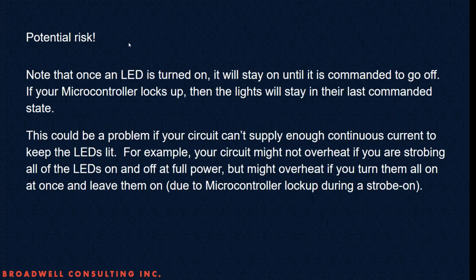One of the things we need to note here is a potential risk. Once an LED is turned on, it'll stay on until it's commanded to go off. If your microcontroller locks up, the lights will stay in their last commanded state. This could be a problem if your circuit can't provide enough current to keep the LEDs lit, or if you count on it being able to turn off periodically to manage your thermals.